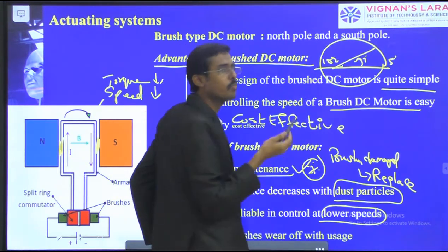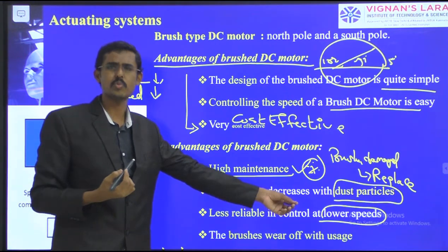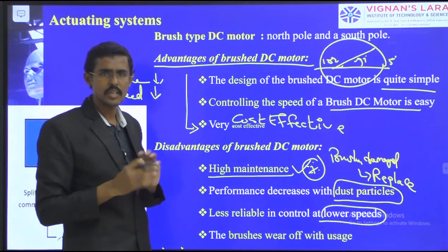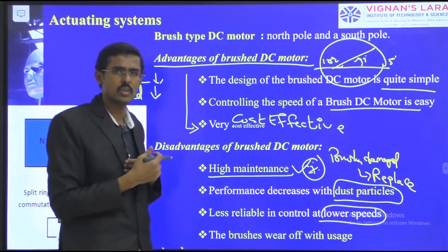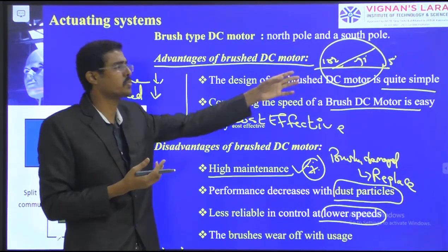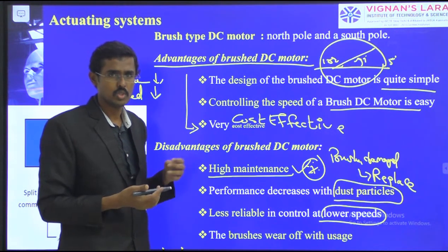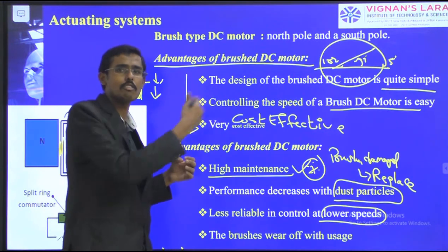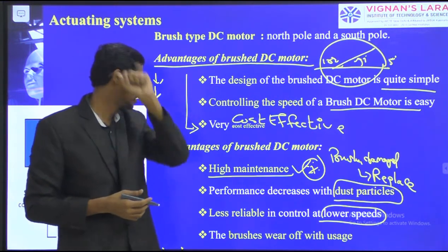So lower minimum angles or minimum slow speeds are not possible. Immediately the armature polarity is applied and it immediately starts to rotate, maybe at medium speed; we do not get the minimum speed in such cases. So what should we do? We should go for other servo motor mechanisms where the minimum angle can be achieved.